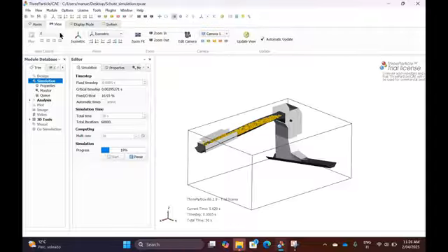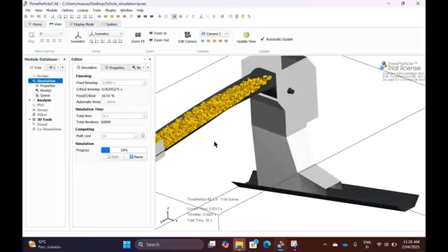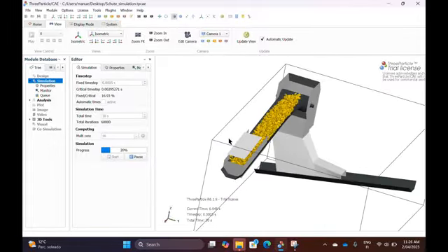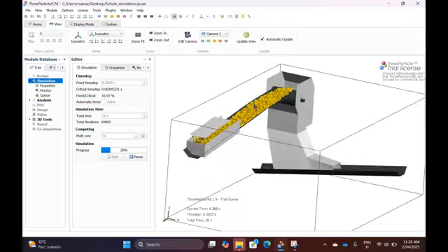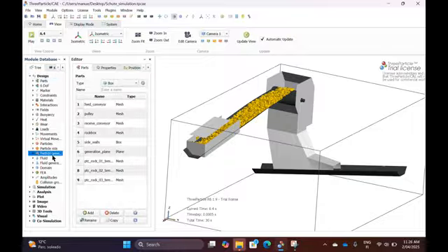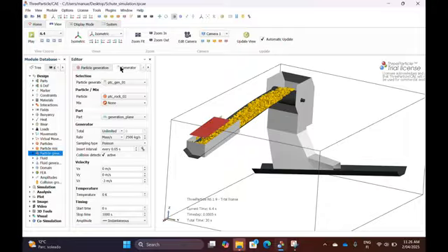And that's important because lots of simulations do not allow that. So if you make anything, let's say a feeder on a screen, and you start feeding the material and say, okay, now it's enough, you can just click on pause, go to the generation rate here, and set that to 0 or just delete it, and save it. And you click on simulate again, it's just not generated.